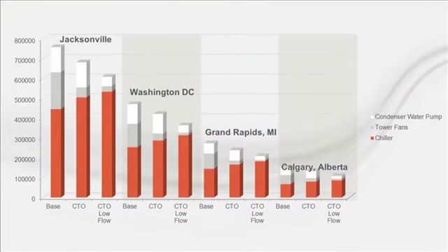In each location, chiller tower optimization saved over 10% of the chiller plus tower energy use compared with driving the tower water temperature down. Then, going to a higher delta T condenser water system saves even more energy and costs less to install. Now, taking a solution to the owner that saves installed and operating costs is about the best you can do. And you can do that in about half an hour.